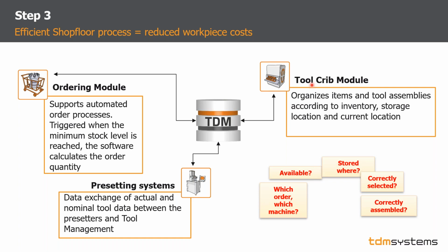So in the end of the day, the idea is to organize your shop floor and also to guide your people to first of all have the right components, have enough components to assemble a tool in the first place, and then of course to assemble it with the right components. And then of course an integration into presetting systems, to send the offset data to the presetter, preset the tool, get the offsets back, and then send the offsets to the machine.